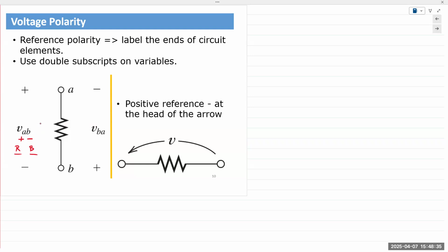Again, the reference point is the most important because that's setting our baseline. That's what we are measuring with respect to, right? So if you're measuring resistors, capacitors, voltages, everything is measured with respect to that point. Current is not measured at the same terminal as voltage. For current, you need to physically change the terminals, but the common point still remains the same. The red terminal is switched out, but the common terminal remains the same. Okay.